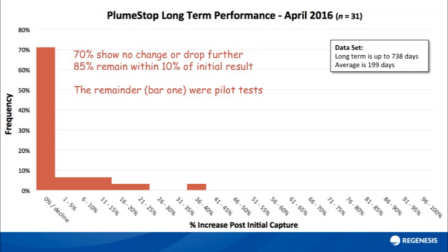We still got an initial reduction, but the sorptive capacity was compromised, and so we found that we were getting more accumulation of some of the breakdown products and less capture of some of the material coming in from up gradient. Again, we'd lost some of the effective dose onto the oils that were already in the ground. Good lessons learned. So let me just take a step back from this for a moment.